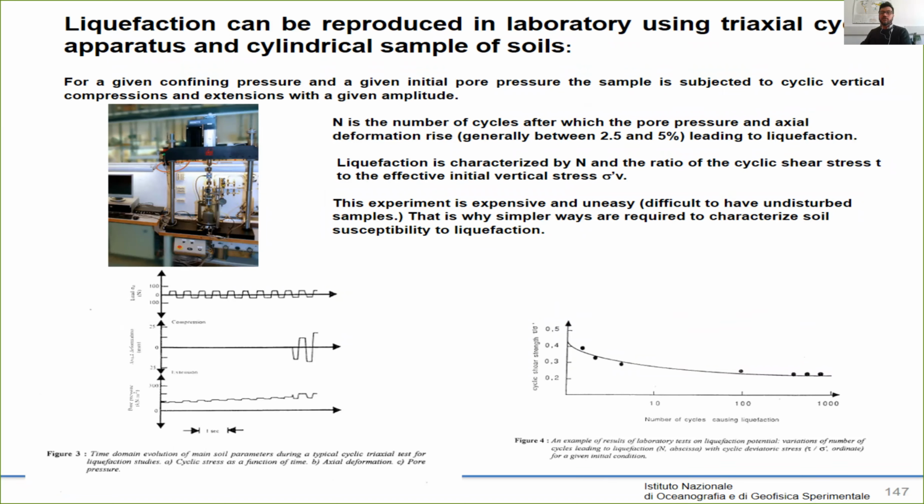So there are tools. Liquefaction has been studied a lot, especially by geotechnical engineers, and a lot with lab analysis. So for example, using a triaxial cyclic apparatus with a cylindrical sample of soil.